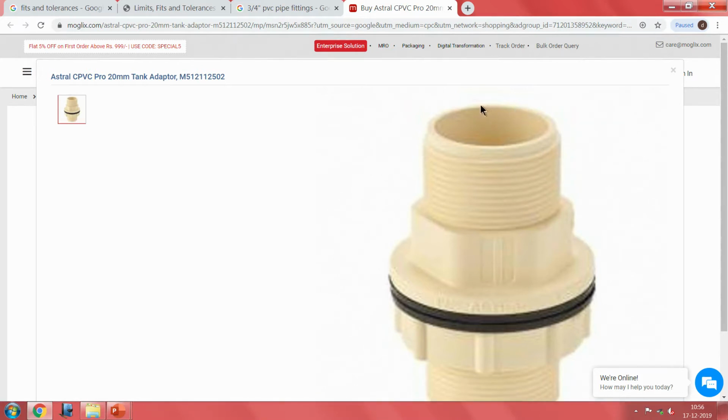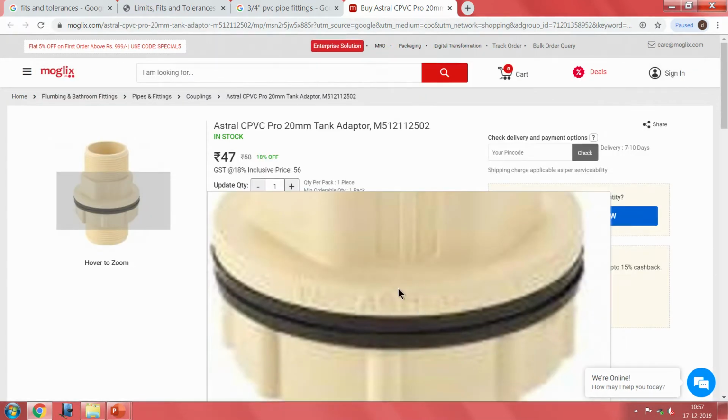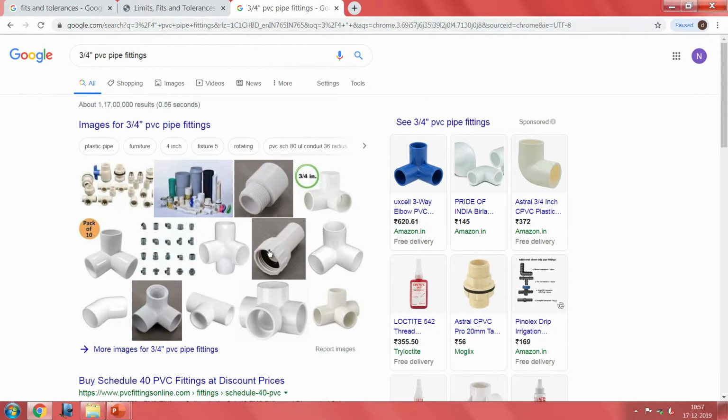Everything is indexed with reference to the internal diameter of the pipe, and from the internal diameter of the pipe you have the threads. If it is sold as a set, often you have a nut here, then you have the equivalent flange here, there is a small gasket, and the whole thing is assembled together across a small plate, and water is not expected to leak. Whatever happens, it is supposed to stay under all conditions.